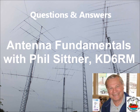If you took your antenna, you had it hanging 66 feet in the air, by the way, at half wavelength, 40 meters. And you went up there and you cut a foot off your antenna on either side, and you were to measure it, you'd find that the resonant point went up, but the feed point impedance is going to stay pretty much the same at that new resonance point. At the old resonance point, that feed point impedance jumps all over the place. And it's just a graphical, visual representation of what happens as you tune an antenna.